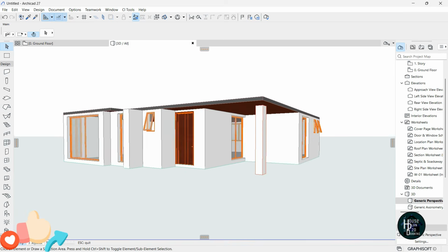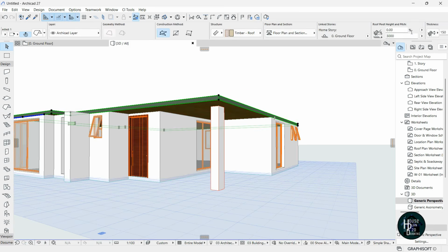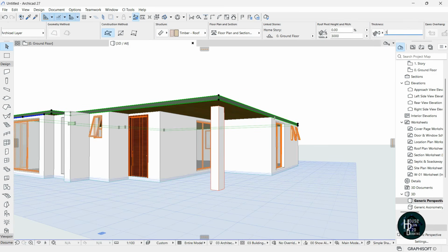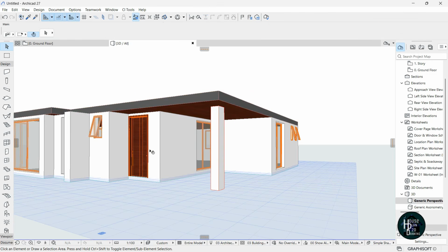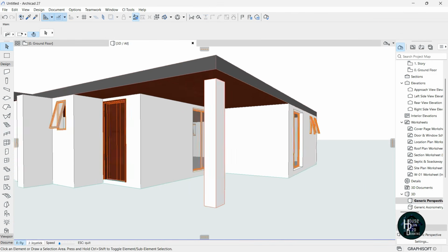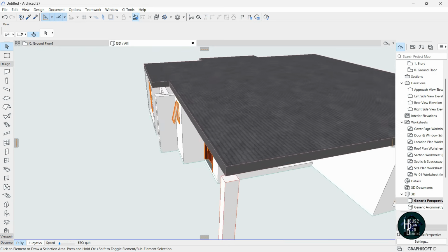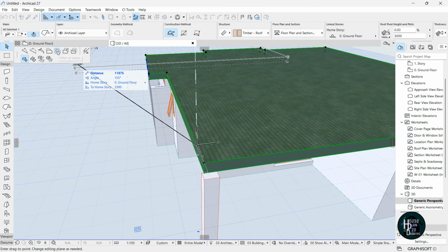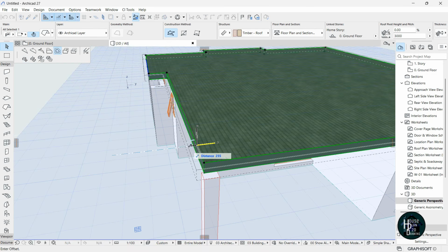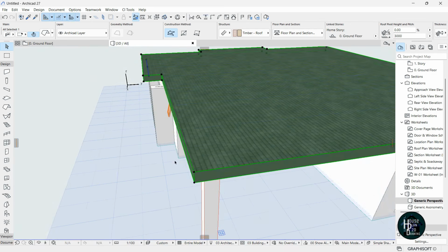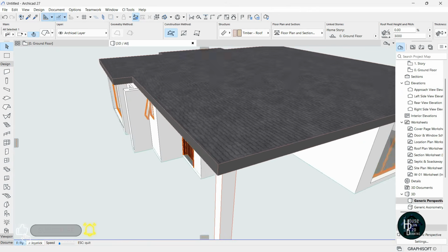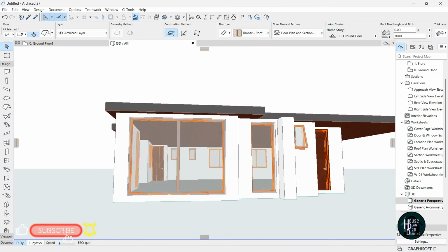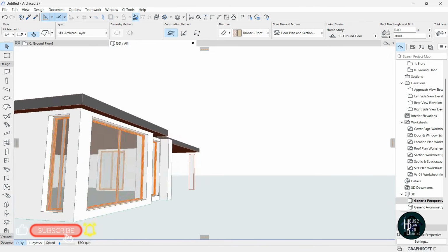and you should have the roof being shown like something like this. Now click this and let's change this thickness here to be 300. Like I said, I was going to edit it earlier on. Now the next thing I'm going to do is click this, highlight this, there's this edge here, click on this edge here. Now come and select this offset all edges. Once you do that, give it a distance of 300, click enter. Now that's going to cancel the rest of the design.